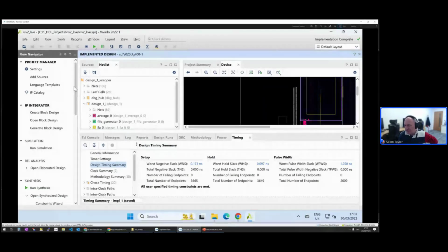and then for those things that come up that are slightly difficult, because no matter how well you simulate something, issues always come up. There are always challenges, and perhaps you're talking to a processor or an external board and things don't quite work so well. That's a good point to start looking at doing ILAs and debugging the design on the hardware.